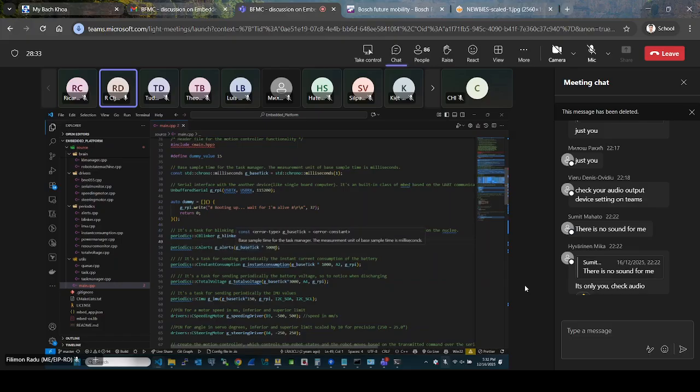The alerts are called every 5 seconds. Also, the alerts is the component responsible for your buzzer. Yes, if you want, you can add notes, but please go inside. We have to go inside the component to show you how we have to structure the code, because as maybe you already know, when you are working with the buzzer, you have to put some sleeps, but it's not recommended to put sleeps inside the embedded platform because it will slow down your entire code.